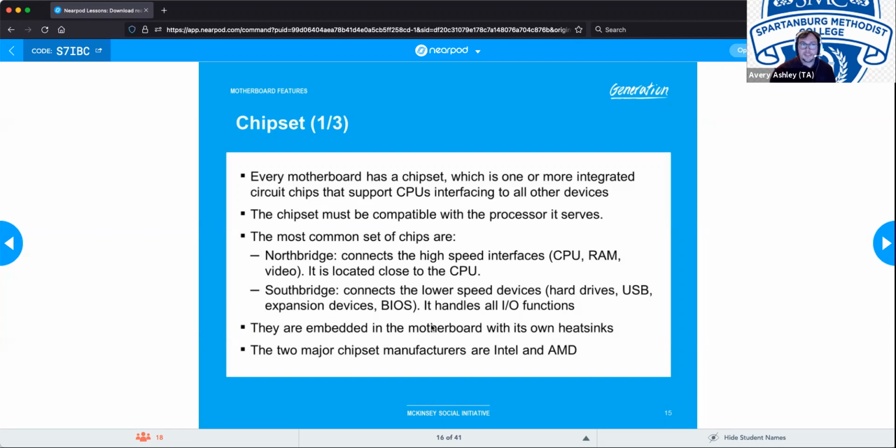But if you put a PCIe by 1 into that slot, it isn't getting extra throughput. It'll still get the same amount as if you put it in a PCIe by 1. You're just using up a slot that could be used for something beefier.